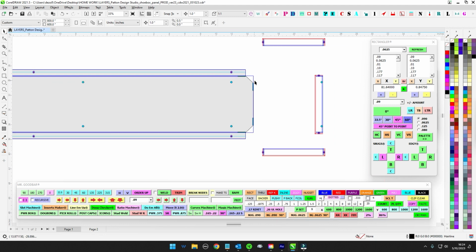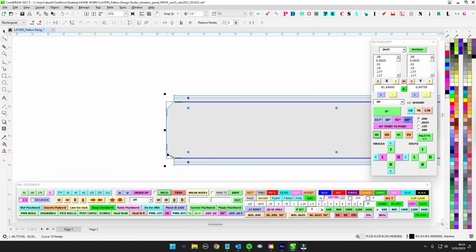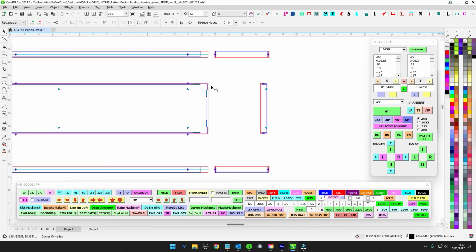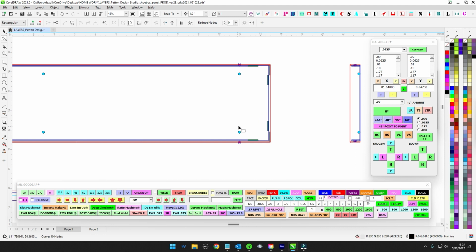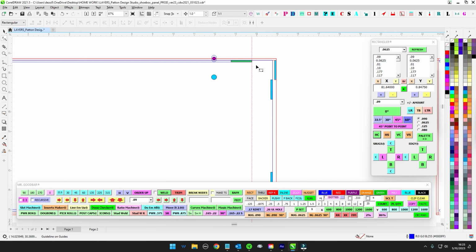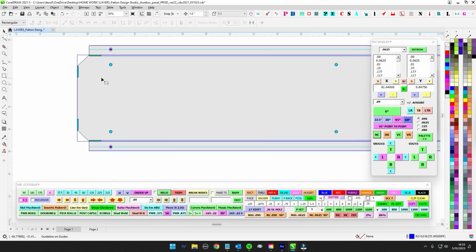Now, what you could do here is go ahead and clip this completely. The reason why you leave this chamfered like this is because of light leaks, and if this was illuminated, there's a good chance that some of the copy would go right to the edge. So you can't clip the backer this much if this was illuminated generally. You would want the backer to go all the way over here, right? And then you would close it off for light leaks and things like that. But because this sign is not going to be illuminated, we might be able to just get away with shortening this and not going down this road.